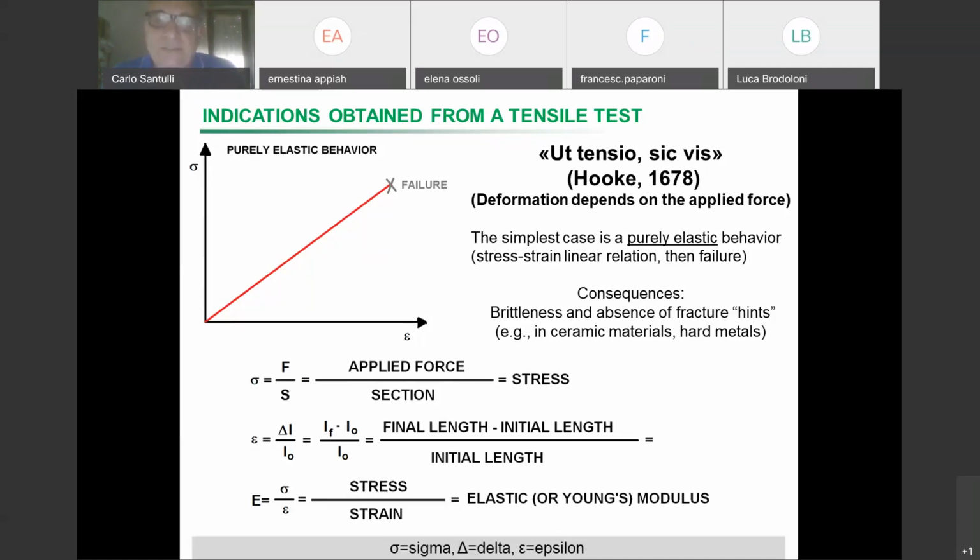The different parts of wood tend to open, and we don't want that, because in the end we don't get any tensile information. Flexural is not that easy, and it's not completely linear in wood.